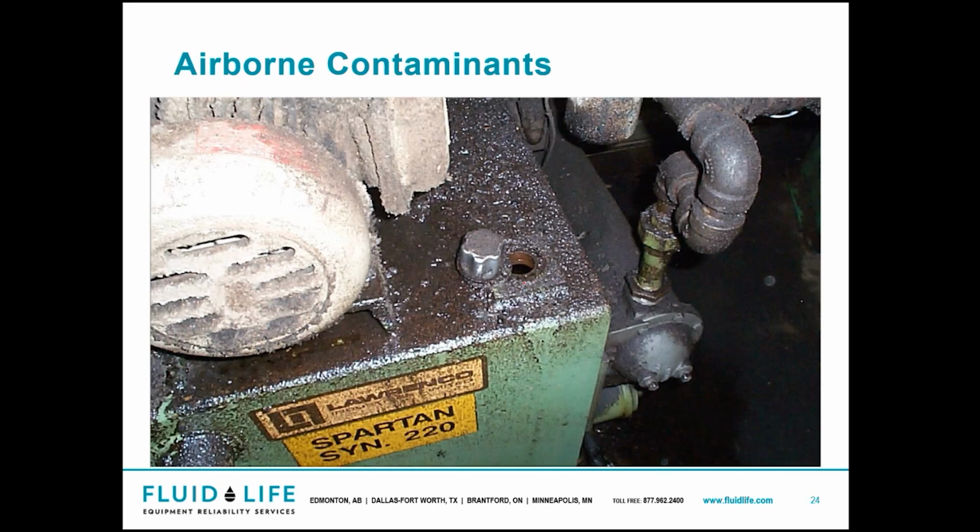So basically what happens is you have a tube that is at a fixed depth that goes in there, and then you've got a proper cap on here, and you'll have a desiccant breather on there, and some of them even have a place where you can quick connect to fill, and on the other side is a place that will draw that oil sample up, and you're always sampling from that exact same spot every time. So I do apologize for my terrible drawing, but that's the best I can do for this right now.